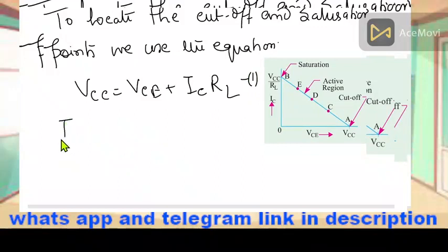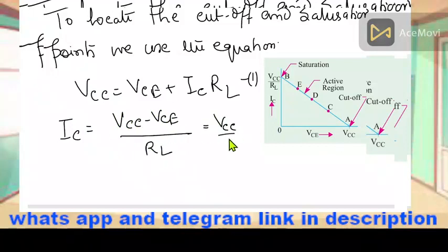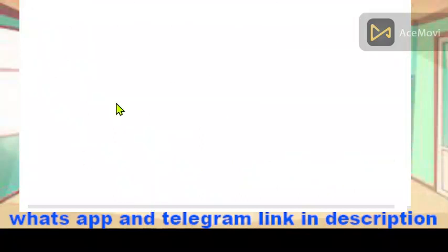So what we have to see, we have to change the equation a small bit so that we can get the quantity on the y-axis in terms of the quantity on the x-axis. So IC will be VCC minus VCE by RL. This is the equation for collector current in terms of VCE, because you are varying this VCE.